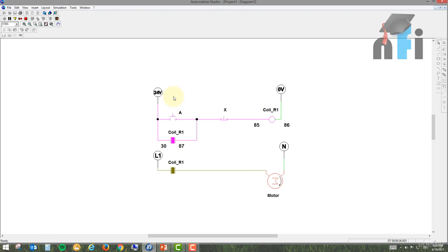Many a times we have a controlling power of 24 volts in our panel, and we have a 24 volt relay, so that's how you will connect it. But high power circuits you generally connect with another pair of common and NO. Or also in case of a three-phase motor, instead of relays or in parallel to relays, we connect the contactor for another level of isolation. We'll see that in the next video, how to use a contactor. All right, see you then.